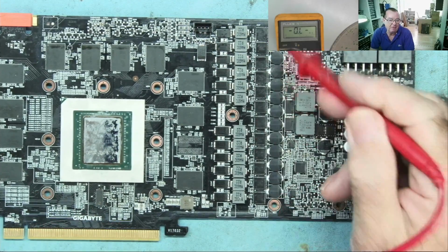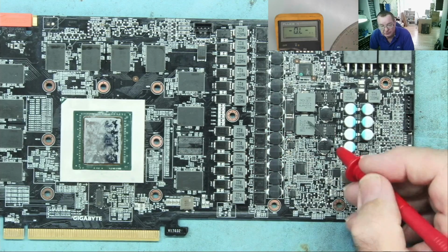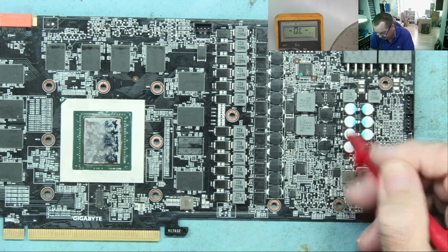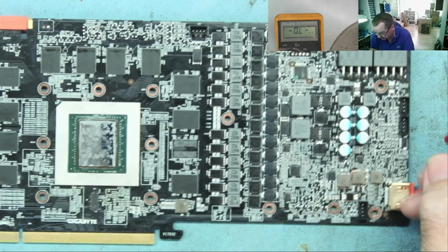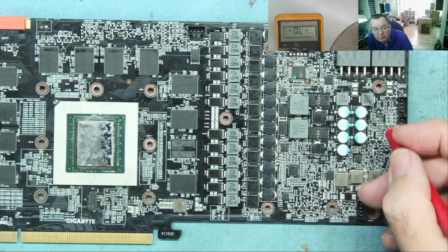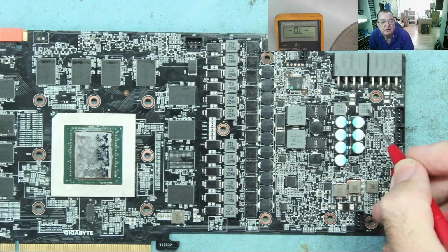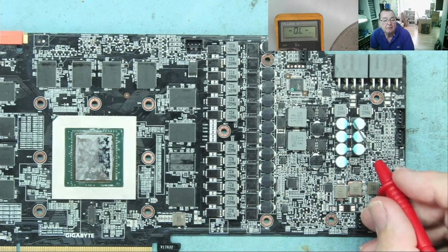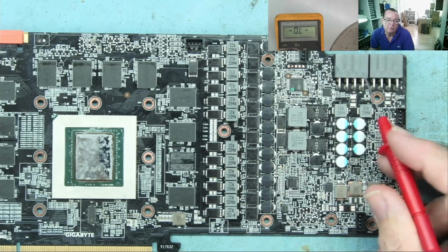This is your Gatling gun I mentioned, your multiple phases, all on the same voltage rail. 2 here, quite hefty ones, quite probably RAM, or one's RAM and one's memory controller. The one here isn't located near any of these MOSFETs, so this is probably a filter. Okay, that one probably a filter as well. There's probably one on each of these.